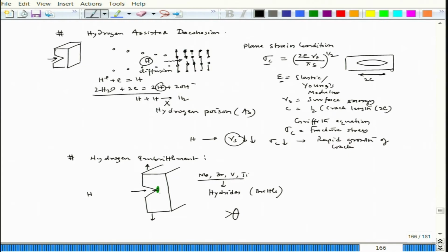So there this crack tip will get blunted. The crack has moved like this and it has got blunted. This blunting happens because of plasticity, or deformation of the crack tip. Now again, a second level of hydrides forms, because hydrogen keeps diffusing in. One hydride layer is broken, the second hydride layer forms, and again the crack moves till the end of the hydride and it experiences the softer matrix, deforms, blunting happens, and the crack stops. That way the crack moves into the material.